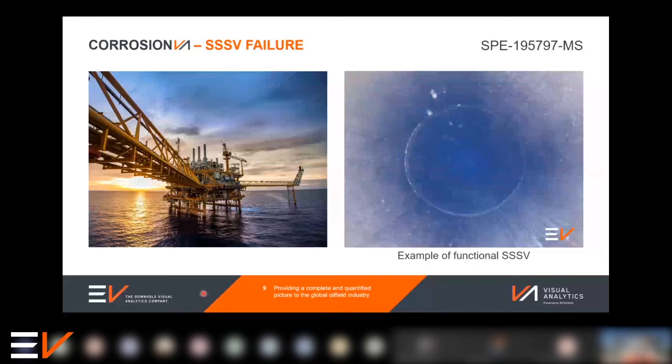They tried to reactivate that valve with some cleanup runs, thinking it could have been scale and deposition or something along those lines, without any success. So without wasting too much time, they then switched to an alternate plan of trying to set a wireline retrievable safety valve in a profile not too far away from the main safety valve. Unfortunately, they had issues in getting that to set successfully. Very similarly to the last case study, it was leaking pressure, and that was found to be at the lower seal bore through a little bit of investigation work.